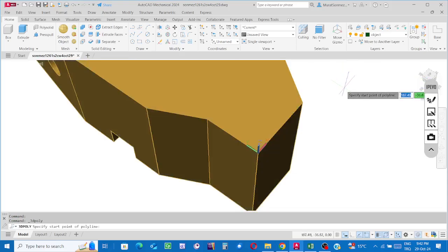After starting the process, the system asks for the coordinates of the first point relative to the origin. For the first point, the reference is the origin, and I remember the abscissa is 80. Click on the comma key. Ordinate is 0. Click on the comma key.